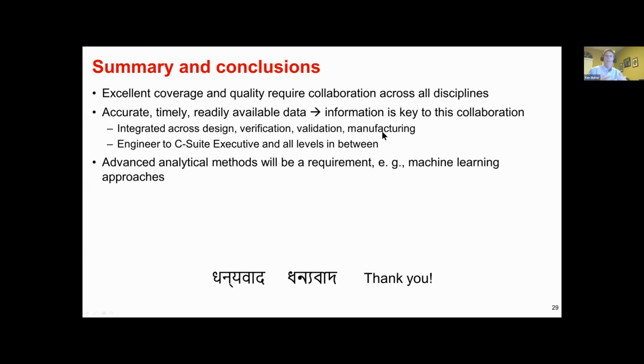And you can use that in an intelligent way to steer test content, so certain portions of the wafer will get different test content, or the types of tests applied will be different than other portions of the wafer, based on an intelligent pre-processing of e-test data to give an early look at what the wafer map looks like and where the hot and cold regions of the wafer are.